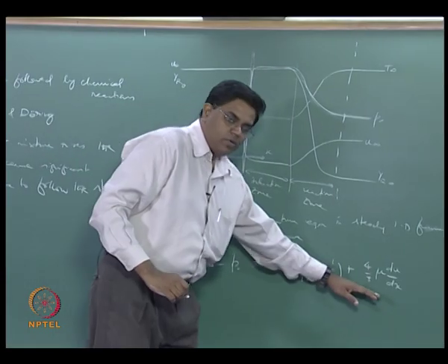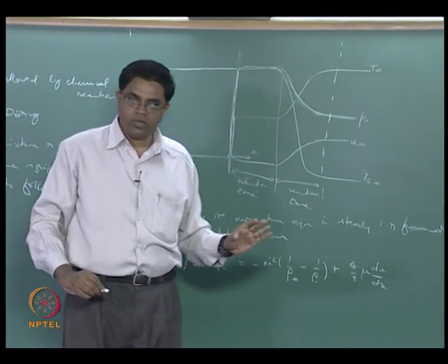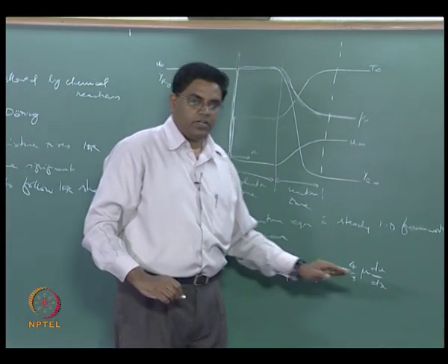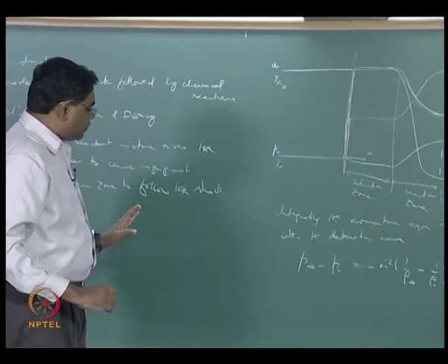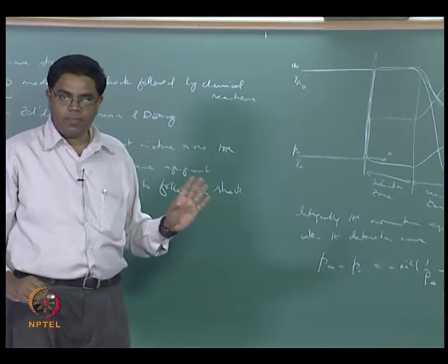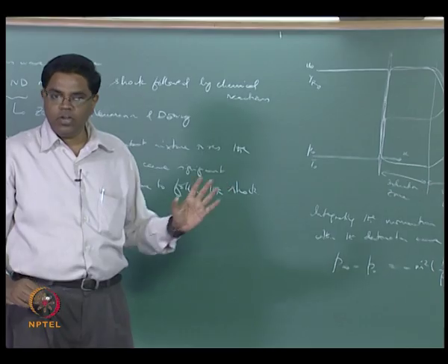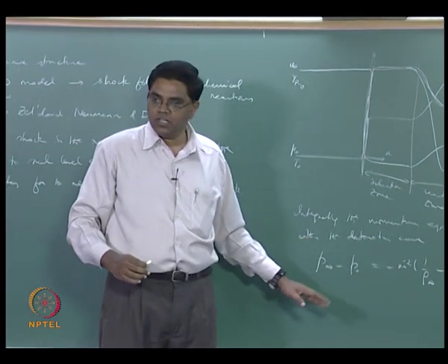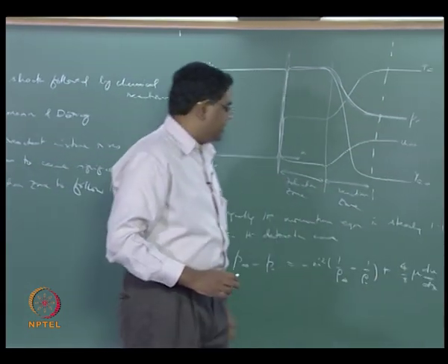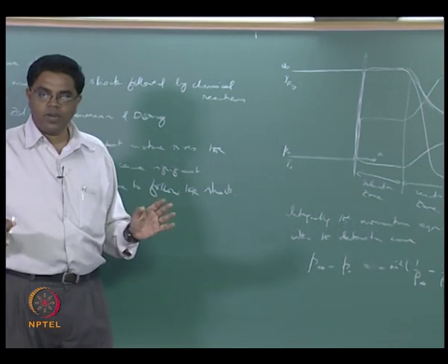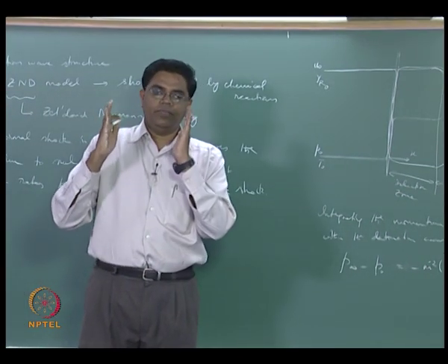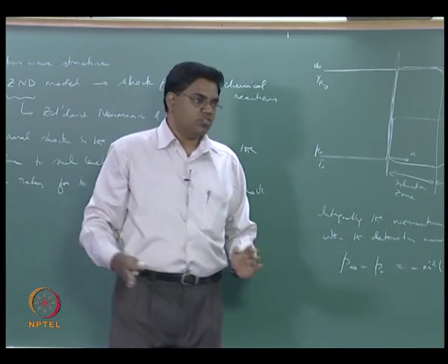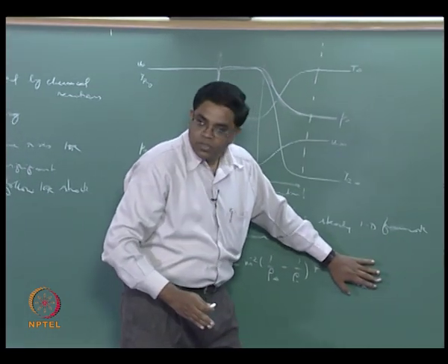When did we get this before? When we wanted to show that when you have very low Mach number, this will actually be of the order of Knudsen number times Mach number, and then the convective term will actually be of the order of gamma times Mach number squared, and so under very low Mach number conditions for continuum flows with low Knudsen numbers, you got a pressure equal to constant approximately. That is when we tried to integrate it once. The next time we integrated it was in the Rankine-Hugoniot framework, but that is like saying all the gradients are within the wave. That means we are looking at outside the wave to get jump conditions, so you do not have the du by dx term at all, right.